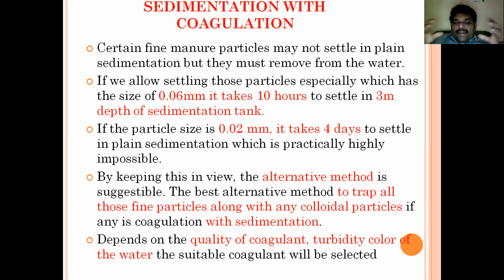In sedimentation practice, the fundamental point is that we do not create any disturbance. If we allow particles of size 0.06 mm to settle, it takes 10 hours to settle in a 3-meter depth sedimentation tank.